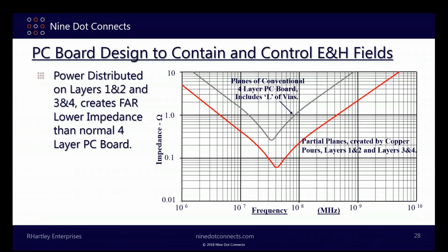Why does that reduce impedance? Because it drastically reduces inductance, and to some degree it increases capacitance. And that drastically lowers power bus impedance, which lowers switching noise and gets rid of countless problems.